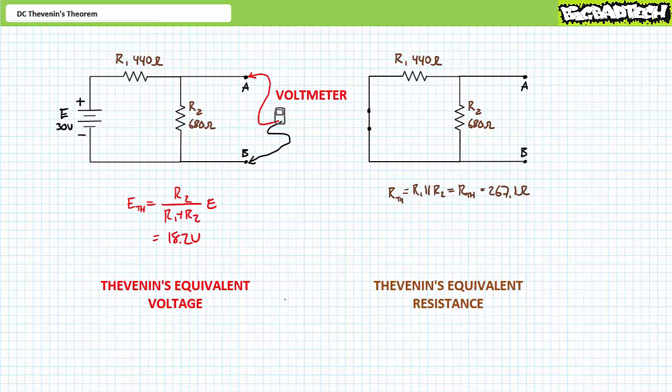To experimentally observe RTH, first one must remove the load resistor from the nodes of interest. Next, one would remove the source or sources from consideration. One removes a voltage source by replacing with a short. Note, do not short out a real voltage source. This is a surefire way to get stuck in the iron chair position for the rest of your academic career. Remove the voltage source first.